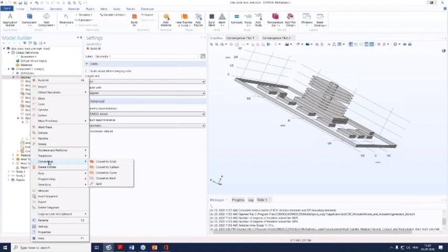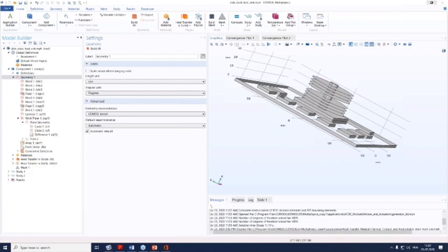But the disadvantage of doing so could be, for example, with convert to COMSOL, whenever you are going to open that geometry, it will get opened with the COMSOL kernel only, and with that, you might be missing some features which are available with the Parasolid kernel or the CAD import kernel. But the imported geometry can be converted into a COMSOL MPH file as well. That's why this convert to COMSOL option is given.